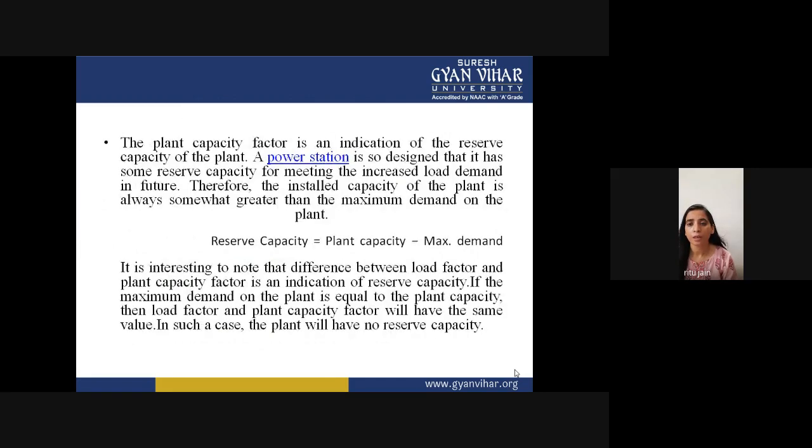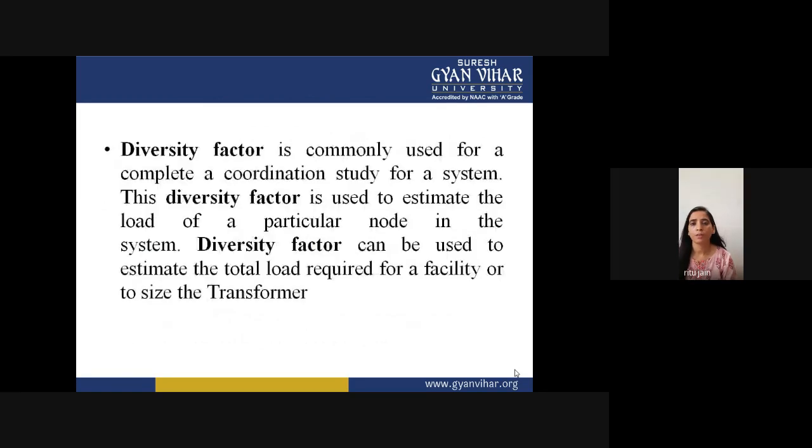If you are able to find out your diversity factor, with different users using maximum demand at different times, then you will be able to coordinate a study for a system. This diversity factor is used to estimate the load of a particular node in the system. So diversity factor can be used to estimate the total load required for a facility or to size the transformer.